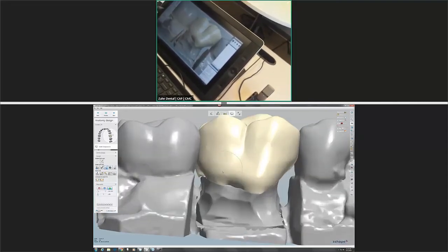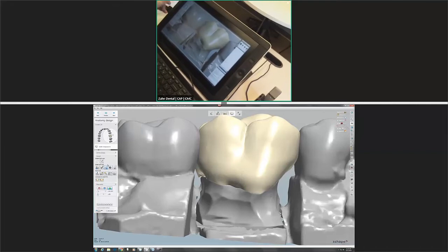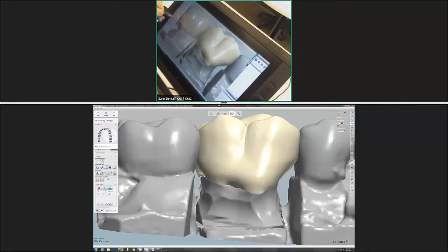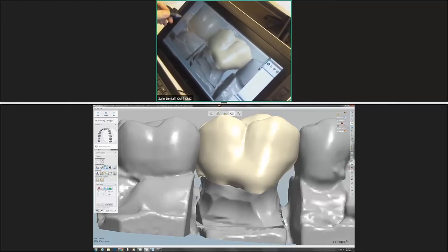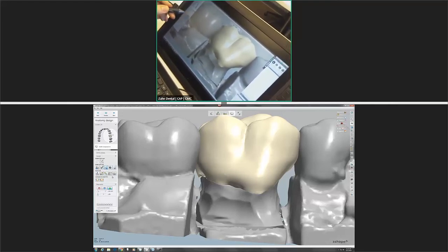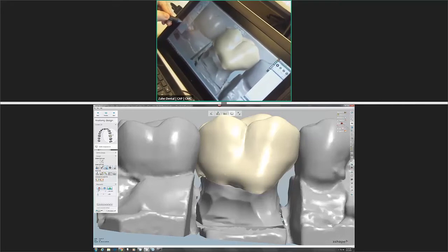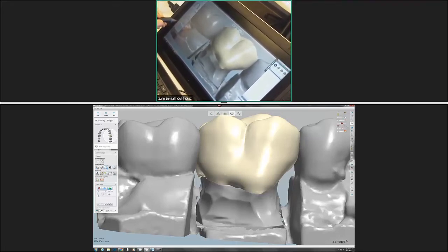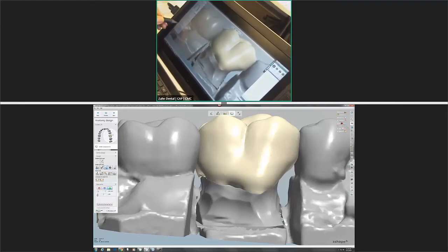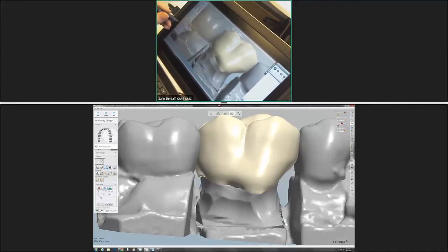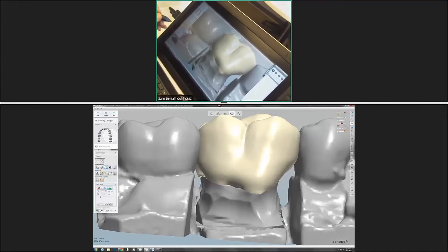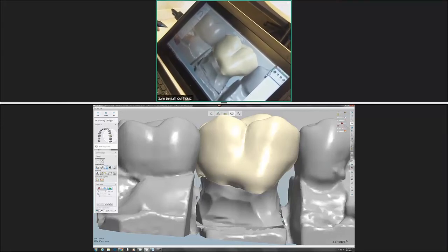Okay, I don't know if you can focus on this. Actually, this is the main function for 3Shape that you need to add. So when you're in the sculpting tool preset here, and you've got your add, subtract, and your smooth tool, right here you've got your intensity, and you've got your draw radius. If you just do a single click on the icon here, it'll actually change to a pen icon.